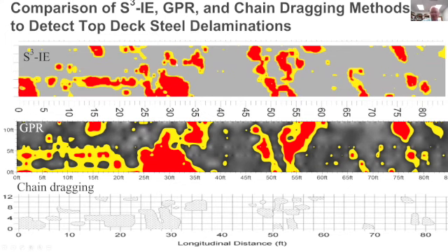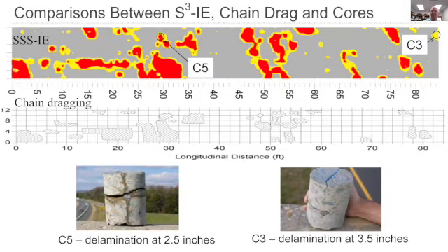The impact echo scanning is the most accurate. And it's really sensitive to the true damage in terms of cracking damage as opposed to the damage potential like radar. Plus it sees full depth if there's not a top delamination. So this compares again when I mentioned they did some confirmation coring, this is in the upper right, the area where the chain dragging did not hear anything hollow. Well, there was a crack, all right, which in fact Echo found, but it was 3.5 inches deep.